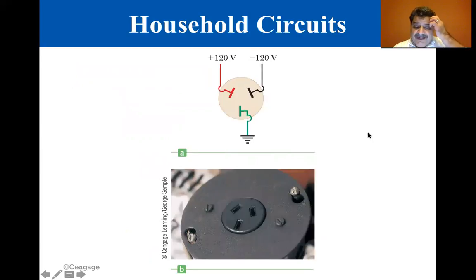Many heavy-duty appliances, for example, electric ranges and clothes dryers, require 240 volts to operate. The power company supplies this voltage by providing, in addition to the live wire that is 120 volts above ground potential, another wire also considered live that is 120 volts below ground potential. That means the potential drop across the two live wires is 240 volts. An appliance operating from a 240 volt line requires half the current of one operating from a 120 volt line. Consequently, smaller wires can be used in the higher voltage circuit without becoming overheated.